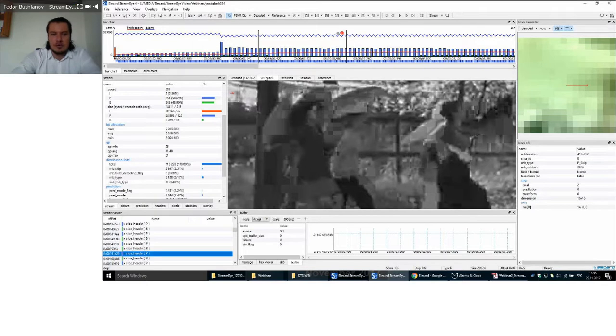Those borders do not look good to human eyes. So there is a filter called the deblocking filter. It analyzes pixels on the borders and smooths them out in order to make the picture look better to our eyes. And when we apply the deblocking filter to the unfiltered picture, we finally have our decoded picture.